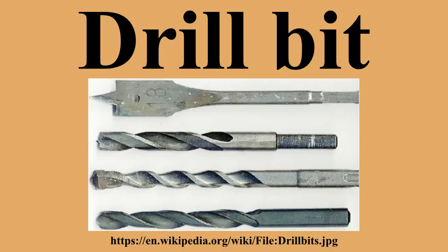In either use the name seems appropriate, as the bit is either establishing the center of a hole or making a conical hole for a lathe center. However, the true purpose of a center drill bit is the latter task, while the former task is best done with a spotting drill bit.